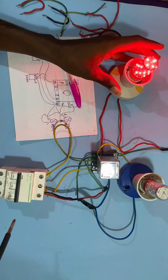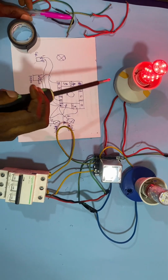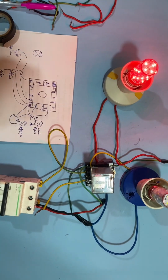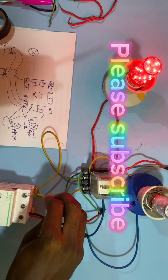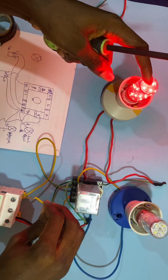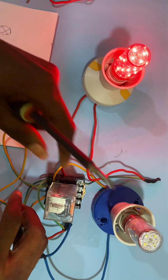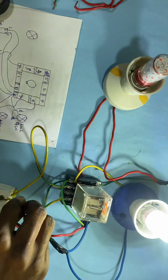Alright, so at this point you see the normally closed remains normally closed, which was our generator. So now our generator is in. So assuming our generator is still in, NEPA suddenly gives their own supply, which is this. So this was the supply from NEPA. Once you slot it in, you see the swapping: it will turn the normally open of this to normally closed, and the normally closed will now turn normally open. So at this point this is normally closed, so it's going to turn it normally open and close this, allowing the current to flow to this other one. So let's check. That is it.